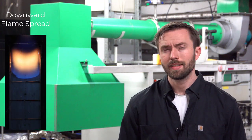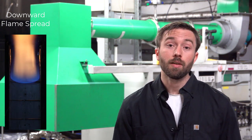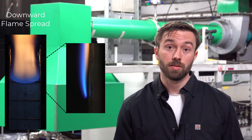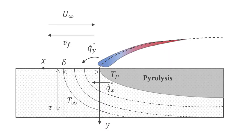Let's start by focusing on downward spread over solid fuels to contextualize the flame spread problem. What we see here is the leading edge slowly working its way down the fuel. And if we take a side view, what we'll see is a boundary layer type flow attached to the solid. Now let's focus on the region within the solid at the leading edge and take a closer look. Here you can see a cross section of the solid with the flame anchored above the surface. The flame is spreading at the rate of V sub F along the surface, while the entrained air flowing at the surface moves at U infinity in the opposite direction of flame spread.